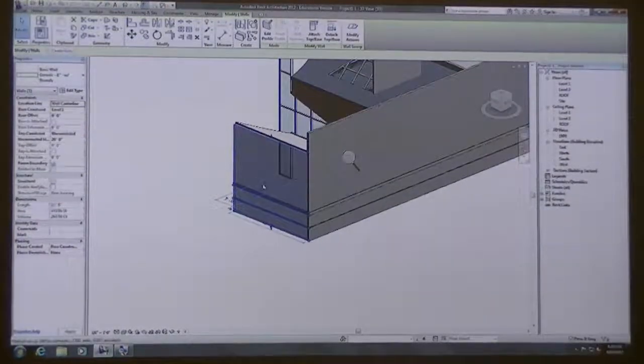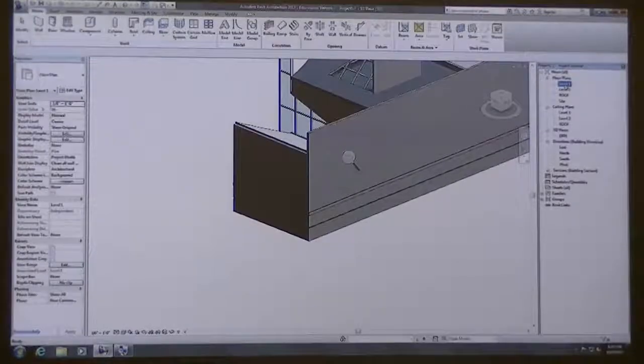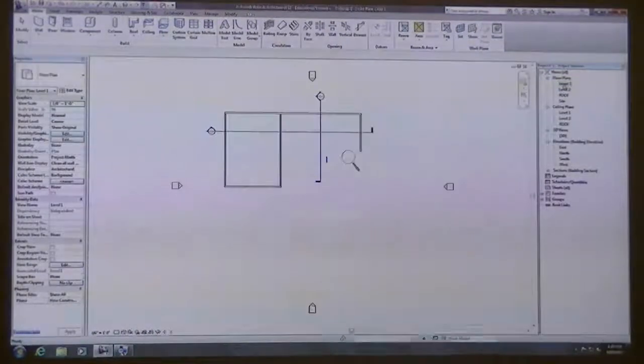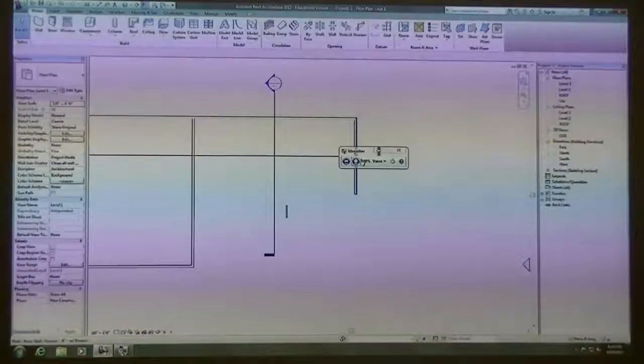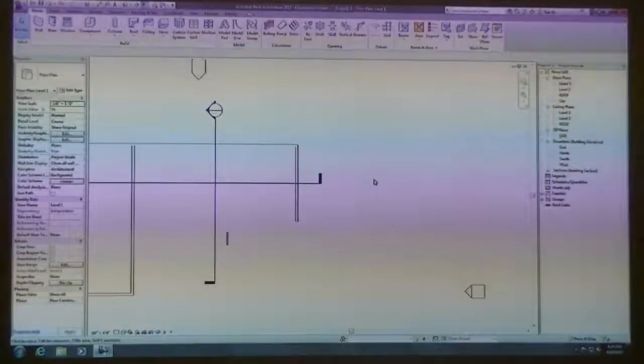You can add reveals and sweeps in another method. The method that I just did there, we can only make kind of these horizontal lines through the wall. That's going to be something that gets built up from the ground up. But if you wanted to do vertical sweeps or reveals every now and then, you don't have that ability to do it in that particular dialog box. The other way to add these components is to look at the wall in elevation.